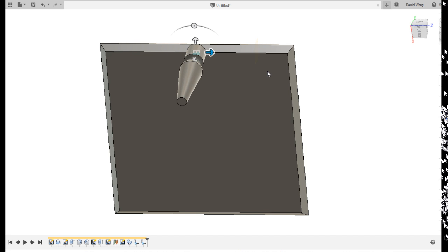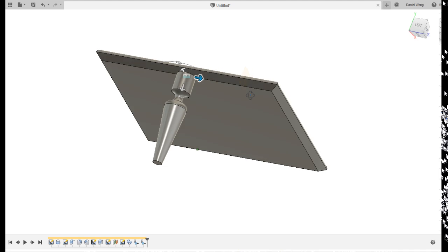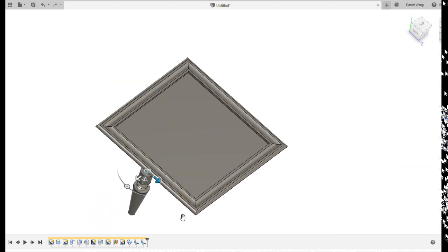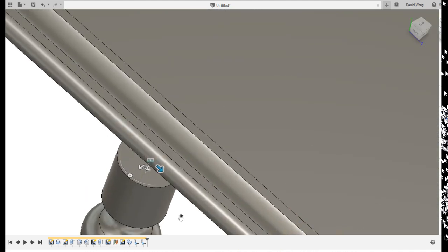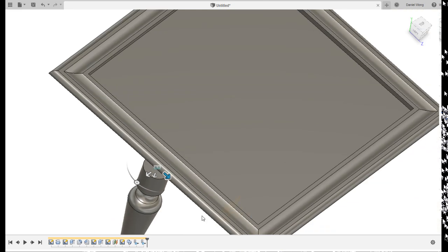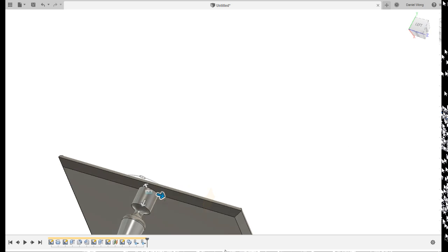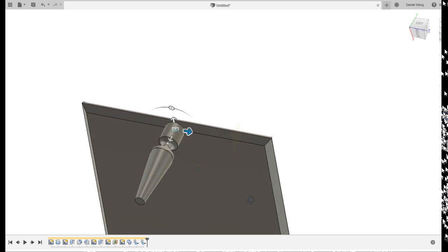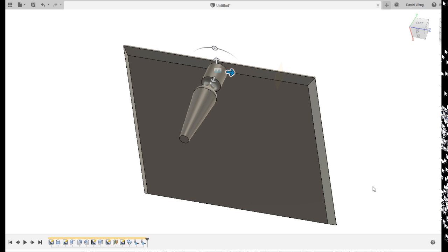And that is just showing that it's rigid, by the way. The reason why it's vibrating is just an animation. But you'll notice that it fixes on the edge here. That's not very pretty, right? No one's going to want that table. We want that to be fixed in place. So what I need to do is create a sketch that represents points under the base face on which I can mount those points to. Does that make sense to everybody?